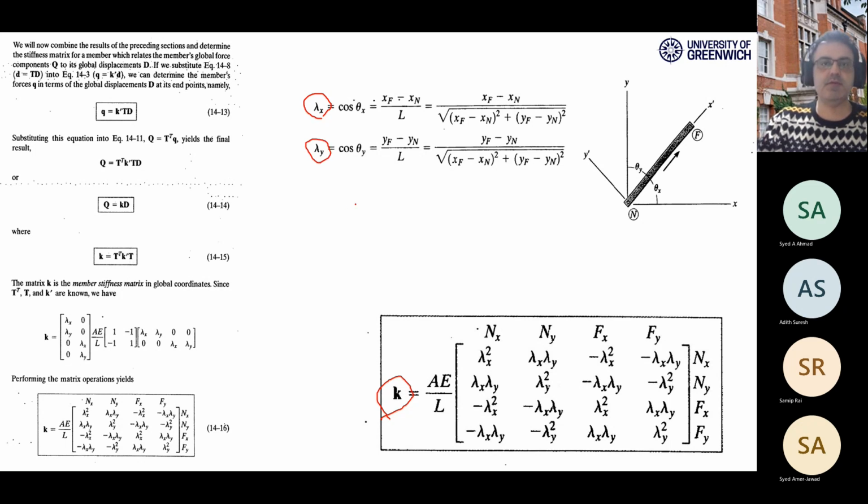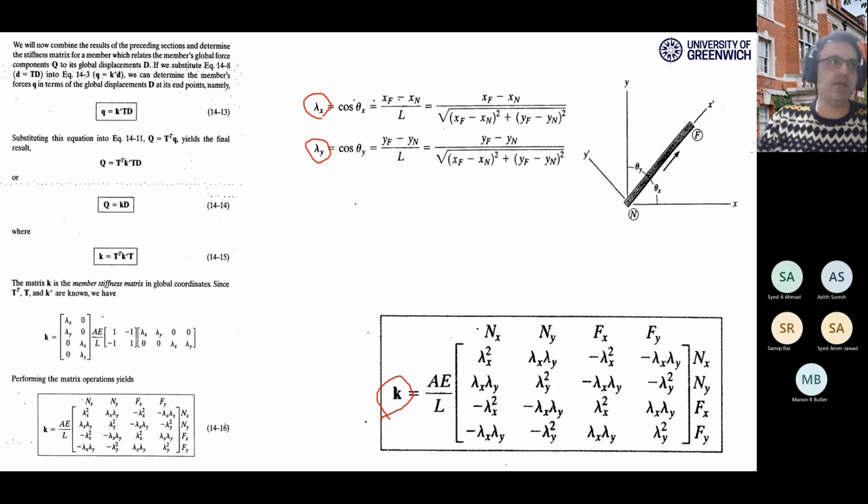It is just coming from the coordination of the points at the end and beginning of different elements. So we write this stiffness matrix for individual elements separately and then try to assemble the whole structure stiffness matrix by putting these individual stiffness matrices into the right places in the bigger matrix.